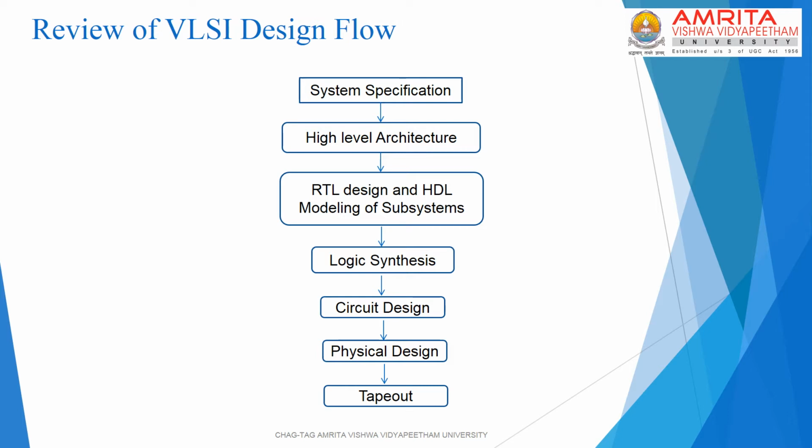And once the architecture is ready, we go to the next stage where each subsystem is designed. And this is where HDL comes into the picture. Each subsystem in the architecture is designed and modeled using hardware description languages like Verilog and VHDL. And for modeling these systems, we have to first represent the design at a level of abstraction which is called the register transfer level, or RTL.